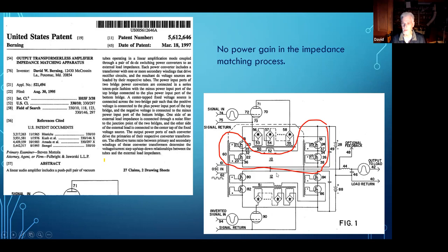And this part would be like switch 5 through switch 8. This is the negative half. The tube on the bottom gets the inverted signal. So these combine, they're in series. So you've got what I call the high side tube, and this is the low side, and then you've got your 2 power supplies in series that power this, and the center is coupled to the return.